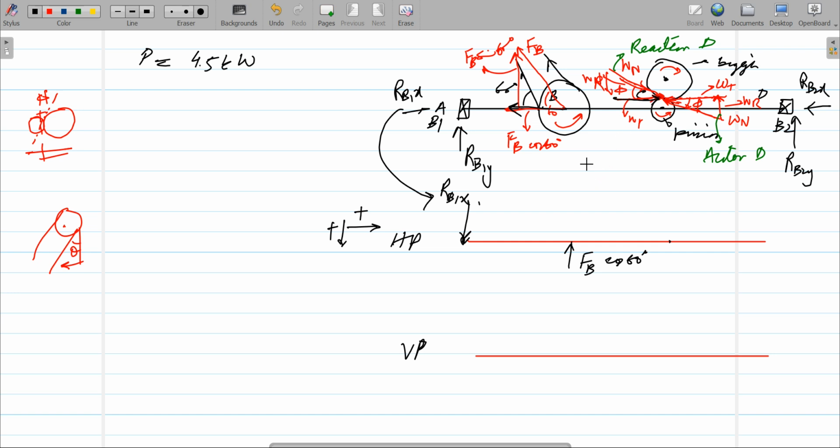Okay, one very important concept here: which triangle to be taken, either the action or reaction triangle. My idea is that the triangle in which the radial force is acting towards the shaft should be used.